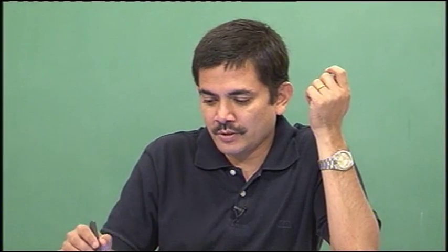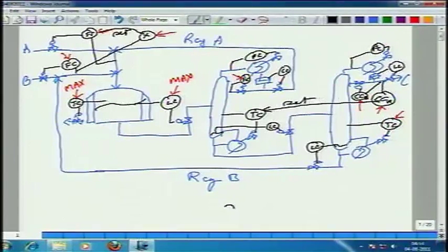See, production is governed by this equation: the rate of generation of C is equal to the rate of reaction times the concentration of A inside the reactor and the concentration or mole fraction of B inside it. This is what governs the C generation rate. So, when I am increasing the total B set point, what is happening to A? K is fixed, temperature is at maximum, and volume is also fixed.